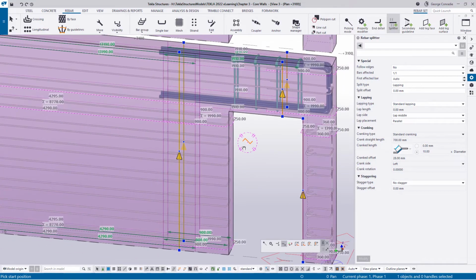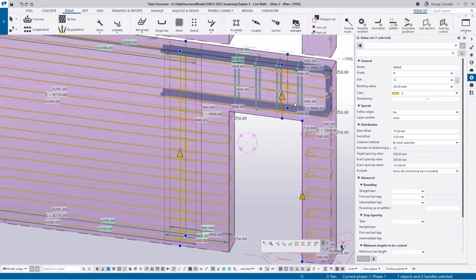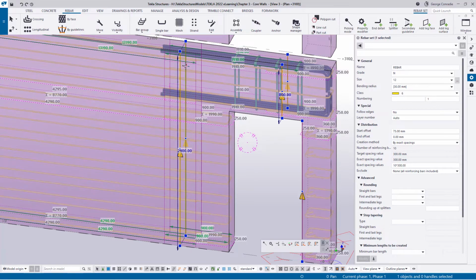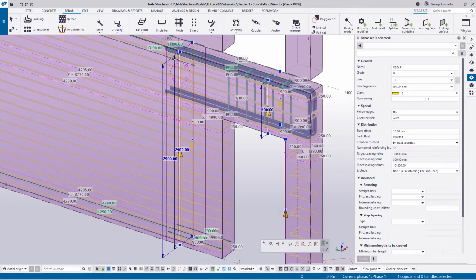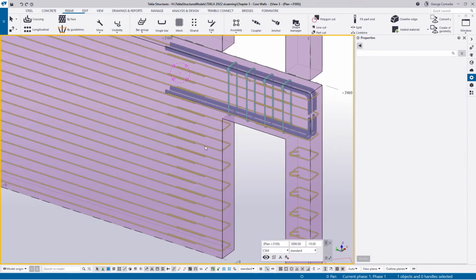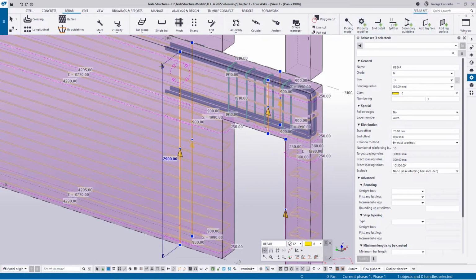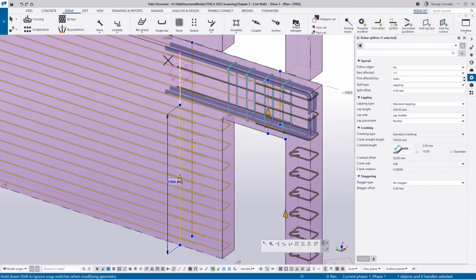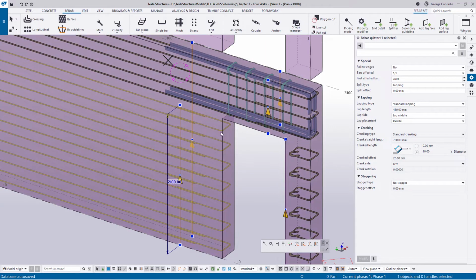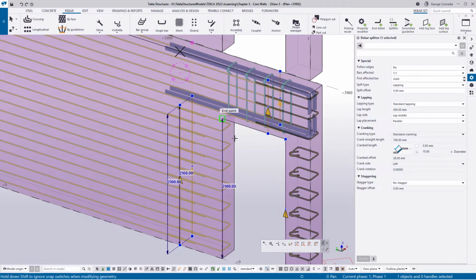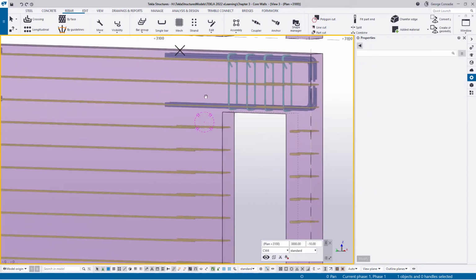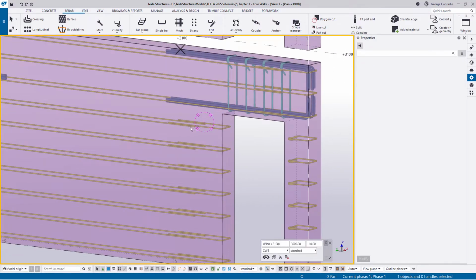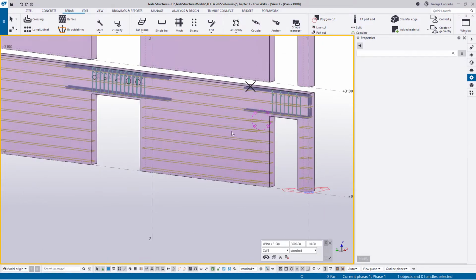But now there's an issue here. It's split all the way to the top, although we've got splitters here. Now what we can do is hover over this line, then grab this arrow and bring it down to the top of the doorway there. And then do the same with that one. Grab that arrow, bring it over to the top of the door, and now you can see that split the ends there. So that's a U, and this one continues, and the U is only there. So that sorts out all of that.